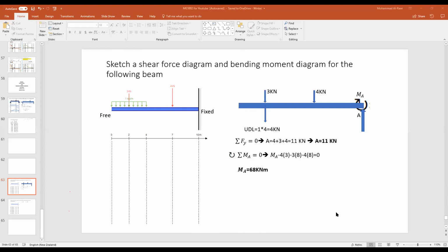Yes, I answered that. If the support reaction is 11 kilonewtons, that's a support force reaction, so we must say force reaction. If it's a force, it's 11 kilonewtons. If just support reactions, then we have a moment and a force. Any more questions, or do we move to the shear force diagram? All right, I can't see any more questions, so I'll come back to the chat after we finish the shear force diagram.